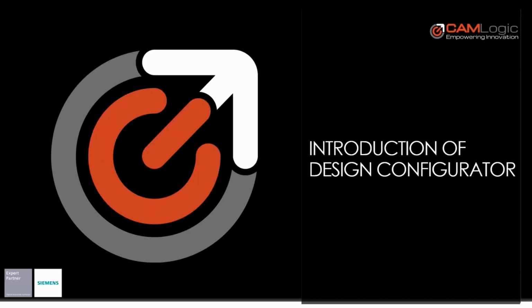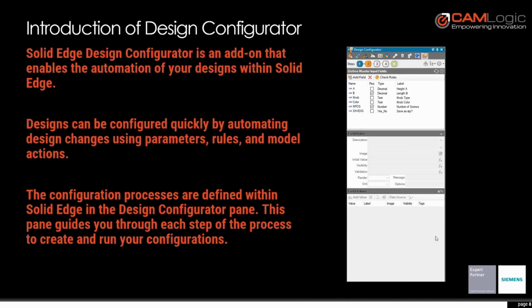So today I'm going to be covering Solid Edge Design Configurator, a little bit of an introduction into the Design Configurator add-on for Solid Edge. First thing is that the Solid Edge Design Configurator is an add-on that allows you to automate your designs within Solid Edge. You can configure your designs quickly by automating design changes using things like parameters, rules, and model actions.